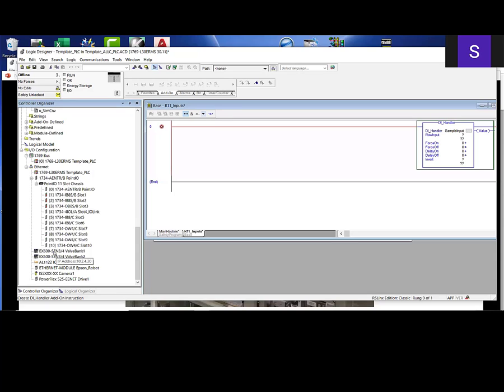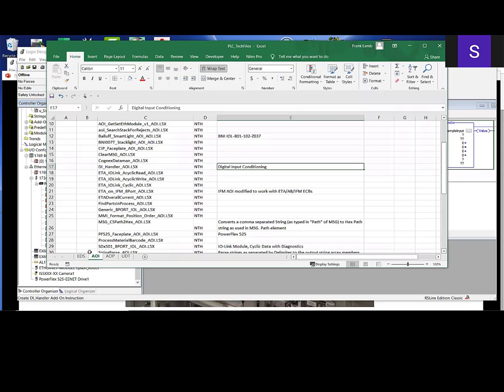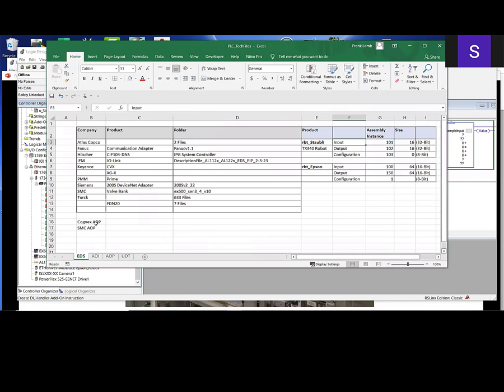So what else did I put in here? I put 2 valve banks. These once again came from these EDS files. If I were to give somebody this program and just hand them the program and they didn't have these EDS files that I had also had to give them, and they are not imported in here. They have to be on people's PLC already. So they're going to have to import the EDS files, and this is a list of all the EDS files that are available, and you'd have to go import them.